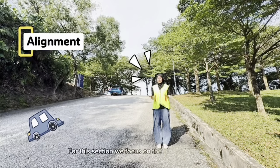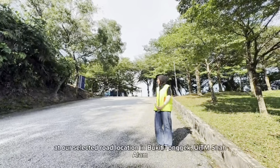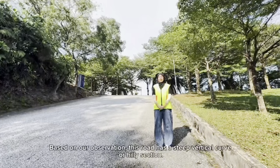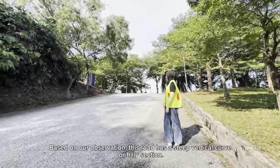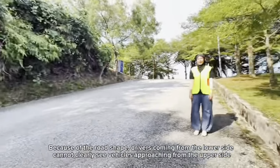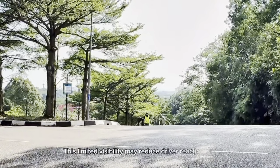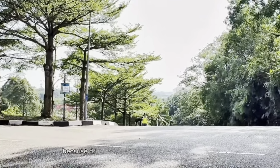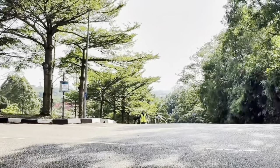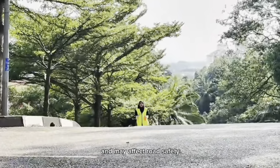For this section, we focus on the alignment aspect at our selected road location in Bukit Tonggek, UiTM Shah Alam. Based on our observation, this road has a steep vertical curve or hilly section. Because of the road shape, drivers coming from the lower side cannot clearly see vehicles approaching from the upper side. This limited visibility may reduce driver reaction time because drivers only become aware of other vehicles when they are already close to each other. This condition can increase the risk of sudden braking and may affect road safety.